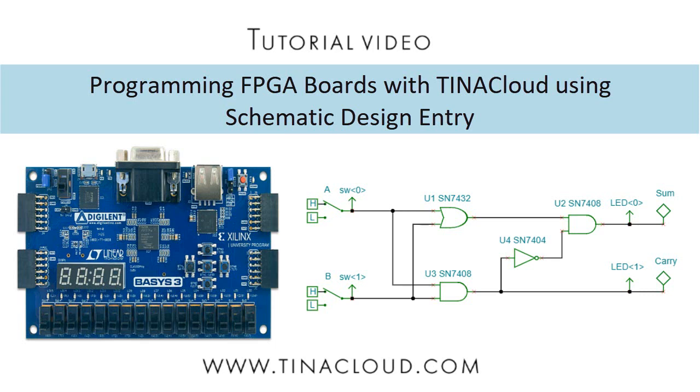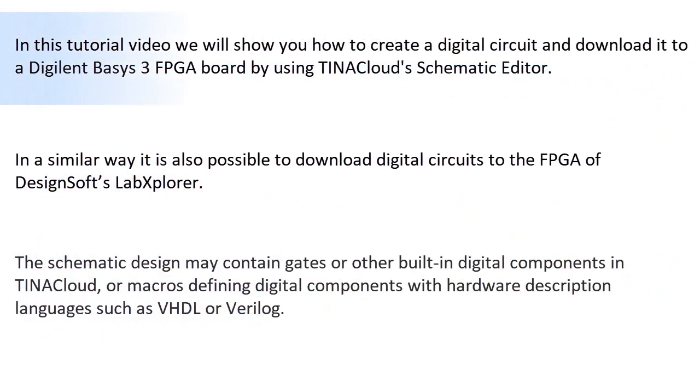Programming FPGA boards with TINACloud using Schematic Design Entry. In this tutorial video, we'll show you how to create a digital circuit and download it to a Digilent Basys 3 FPGA board by using TINACloud's schematic editor. In a similar way, it's also possible to download digital circuits to the FPGA of DesignSoft's Lab Explorer.